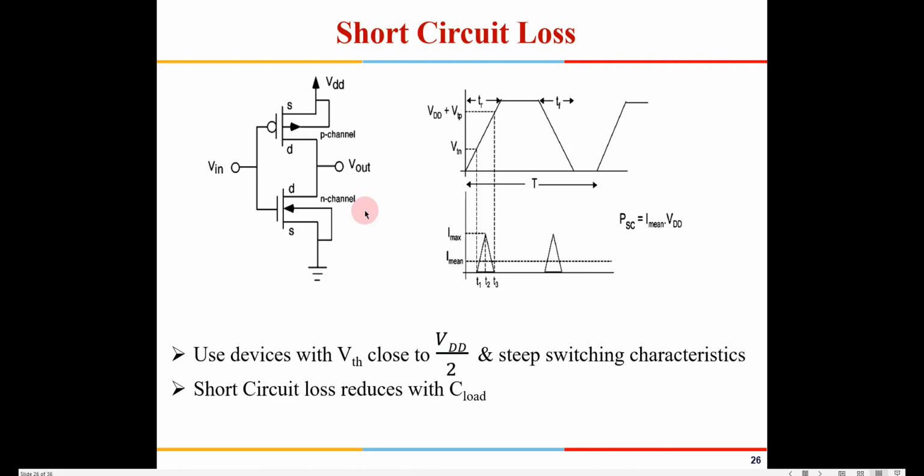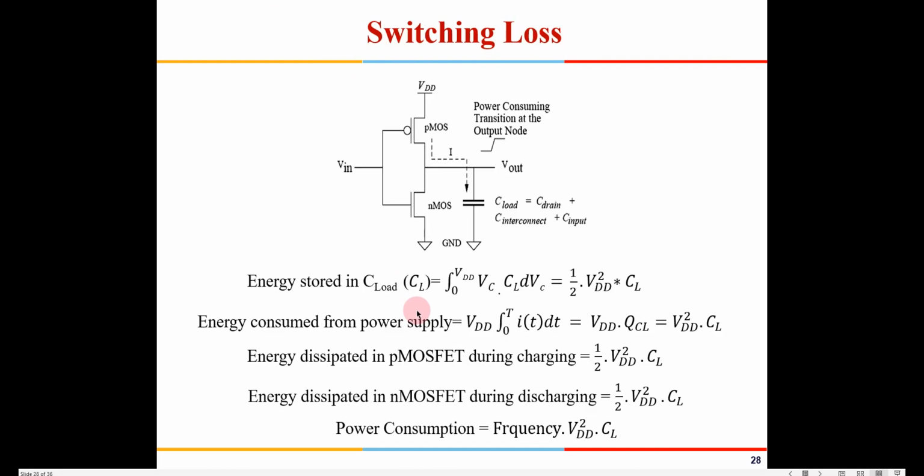So you can afford to use a higher VT in that non-critical path, the 3 gate path. Whichever path has the maximum number of gates and the largest propagation delay is known as the critical path, because you have to wait for that output to come. So in a non-critical path, you can use a high VTH device.